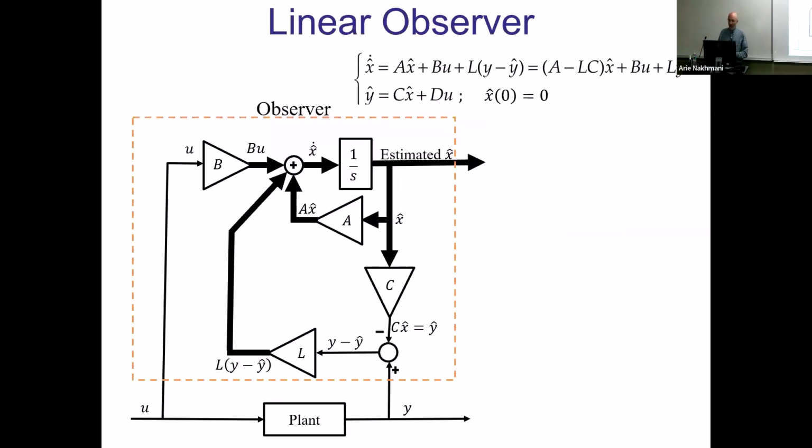And this is how it will look like. Pretty complex, you see. Inside the dotted line, you have that observer circuitry, which is simulating everything. You can maybe recognize that part, if you remember this implementation of the plant where you have N integrators, then you have matrix A, and so on. So you have that initial part, which is exactly as your linear system. But you also have an add-on here.